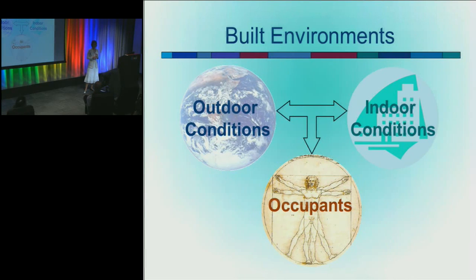With respect to modeling, I can say you're absolutely right. It would be really a daunting task in terms of not just the simulation, but inputting all of these neat, nice details that you have here. So with respect to diffusers and the details in indoor spaces, we spent, I would estimate, 5 years, different research groups, looking at different things, and we have found what's reasonable to put in and what's unreasonable to put in. And the things can be represented, for example, diffusers with their appropriate momentum and mass flow, and the question is just how do you come up with the data from manufacturer catalogs, and we have found that as well. So a design community can really follow the process. You're welcome.